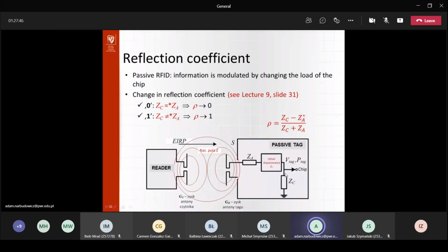So all the power will be dissipated in our resistance ZT here, right? However, we also get the output to the chip here, and what the chip can do is, for example, make a short circuit to the ground by effectively bypassing this impedance ZT. So that will replace this specific impedance with a short circuit, right? And we already know what will happen. We have done this calculation before.